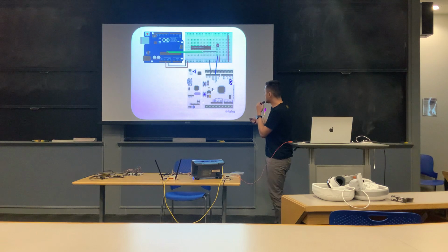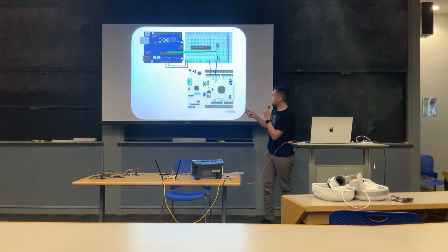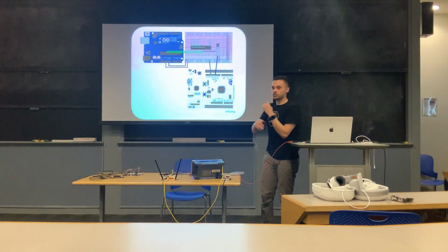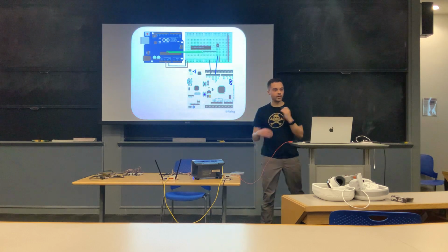And so this is what's going to control our injection, and this is the transistor that will determine when it's active. So when we send a 1 to the transistor, it'll short the clock out. When we send a 0, it'll just let the clock pass through normally. Any questions on the setup?